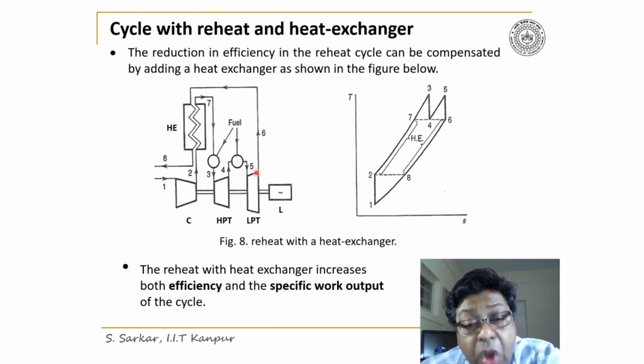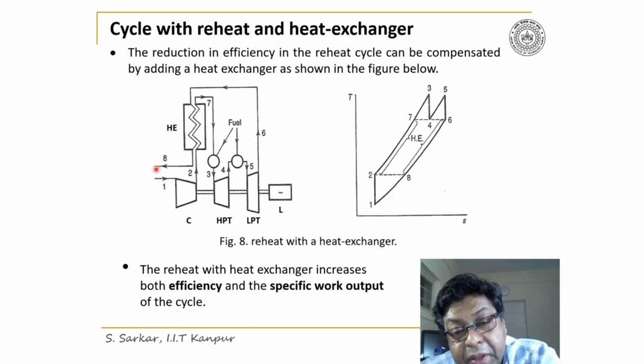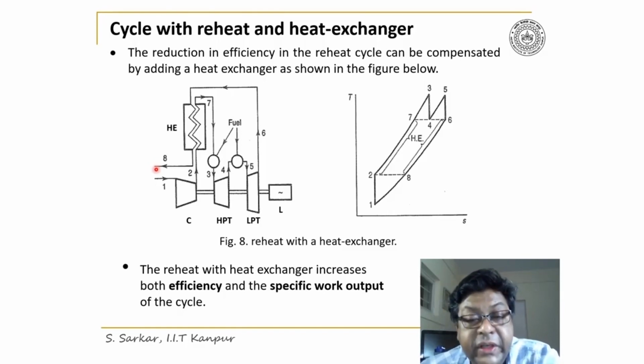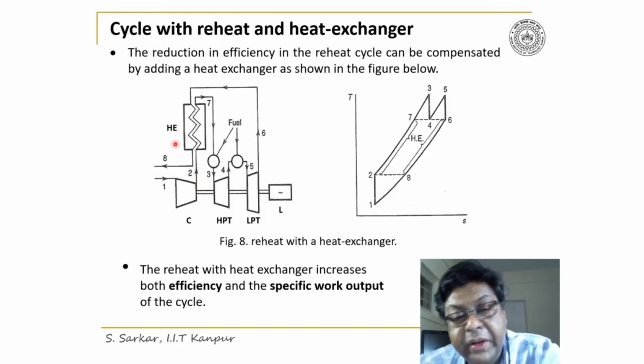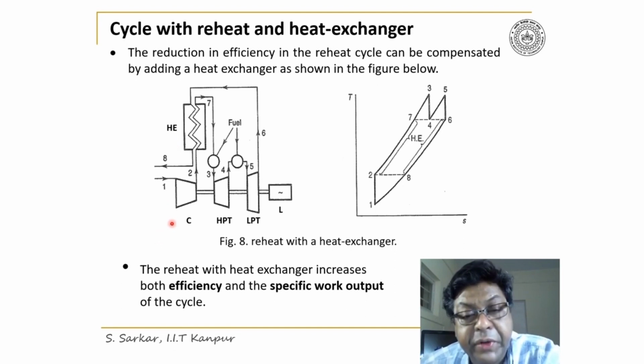Further, exhaust from the LPT is passing through the heat exchanger, and therefore it is utilizing the exhaust temperature, which is normally higher than the compressor outlet temperature. So look here, a heat exchanger between the compressor and the LPT is also provided to utilize the energy.